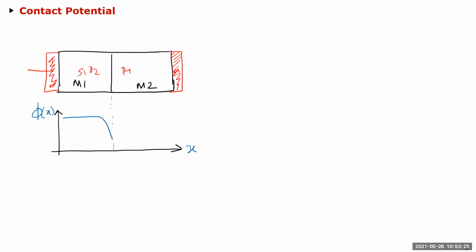Then we looked at what's called the contact potential, and I think a lot of people still have questions about it. Like I said, it's not very intuitive, it's counterintuitive, but take a look. Civitas, like I said, probably has one of the best explanations, so look in that text if you want. Essentially, it tells you the potential which is formed. It's like a built-in potential, but what you see when you have contacts on both sides. When you have the contact, you can measure them. As I said yesterday, if you put a contact, this is metal, and phi m1 minus phi m1 cancels out, so you don't see that, but it's basically the potential you see prior to the contact.